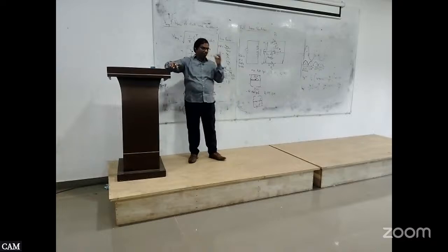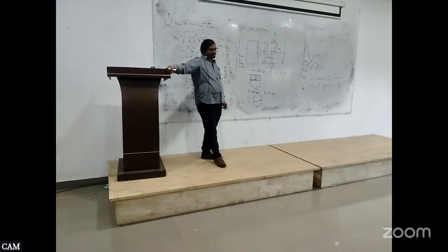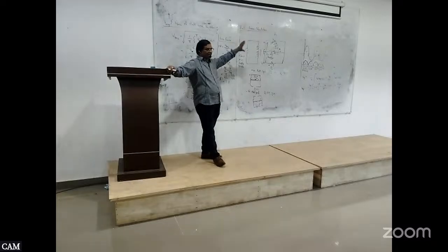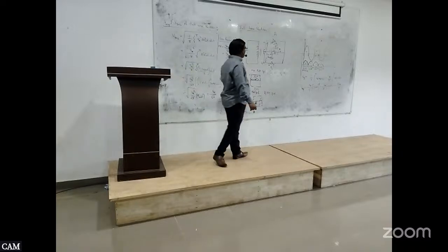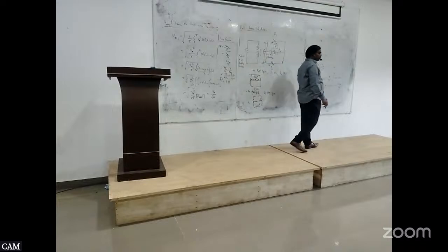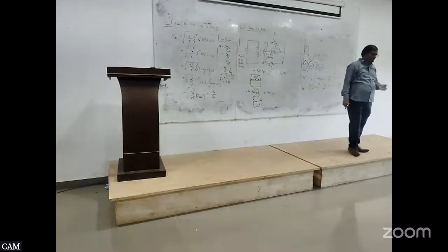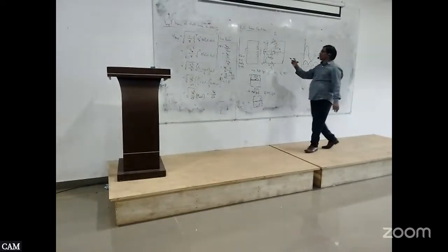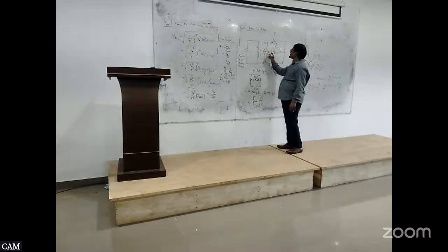After this waveform, we actually have to connect a filter. Full wave rectifier with filter. Your filter is not there. Okay, half wave rectifier with filter: connect a capacitor across the resistor, which will become half wave rectifier with filter. Wherever the capacitor is there for the half wave rectifier, you connect a capacitor there.